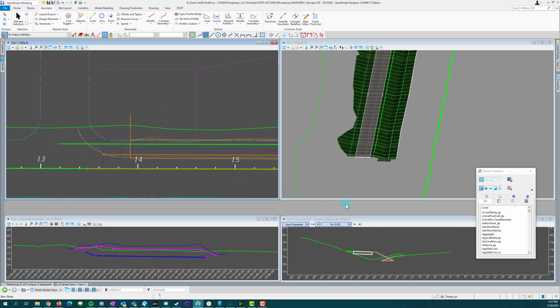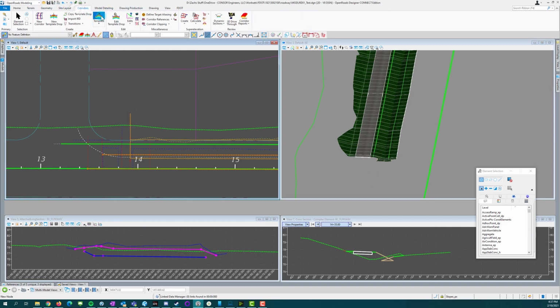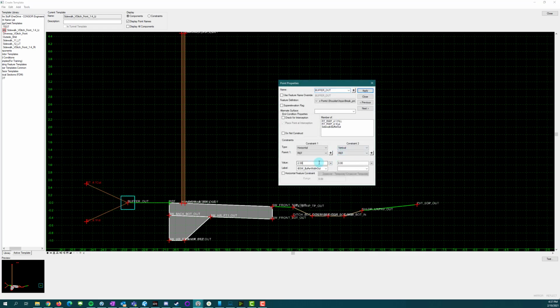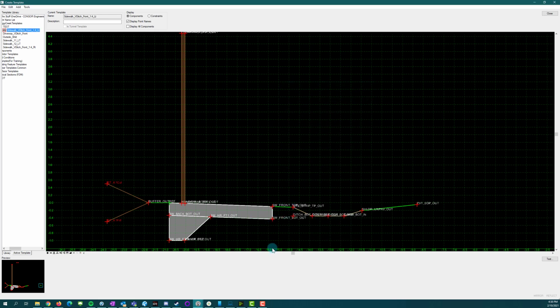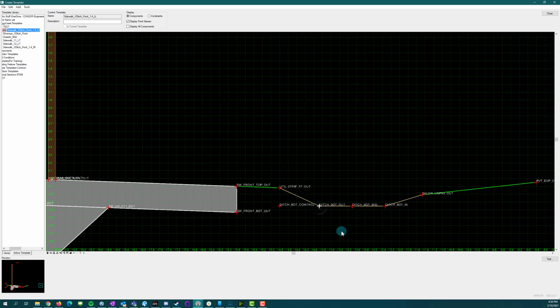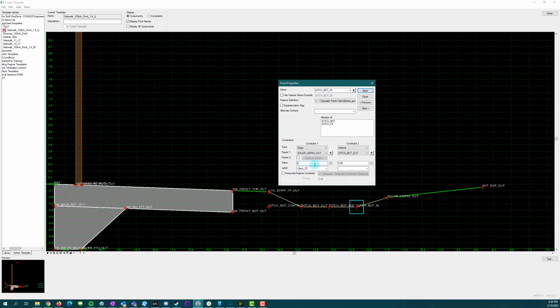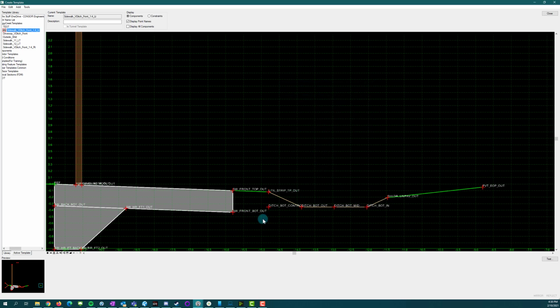But using these tools will allow you to test your work out here and ensure that you're doing all the correct things. So one thing I want to try is to completely minimize this template and see if there's anything we can do in here to make it work. So let's say we wanted to reduce this to 1. Okay, so we're already at 1 here, and we're already at 1 on 4 here. So we probably want to stick with that 1 on 4. I think if we go 1 on 4 here, it's not going to help us all that much because that's already the lower side of the ditch. We can see if that does a little bit. I've already got this dropping at 6%.